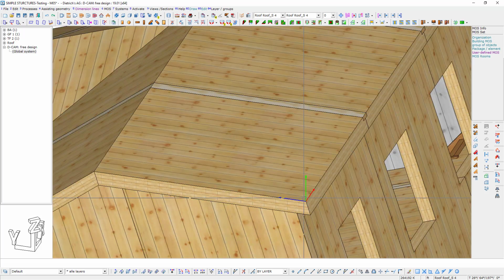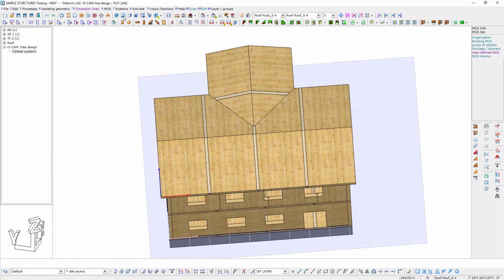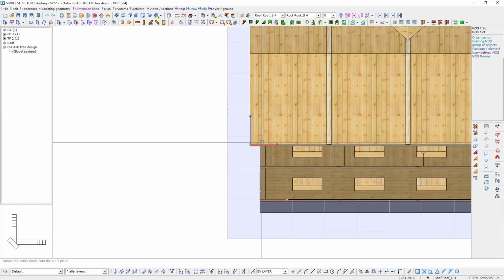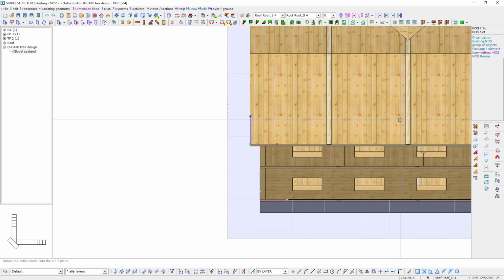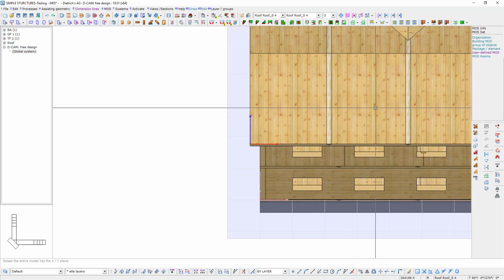handy when you're in here modeling on these roof planes, especially when I can get into this says plan view, but I think of this more as a normal view, or a view that is parallel to this plane. So let's get into that view and see what that looks like. So there we see our normal view. So we're looking flat, straight at this plane right now. And this is helpful when we're modeling on the roof or we're trying to cut a hole for a skylight, something like that.